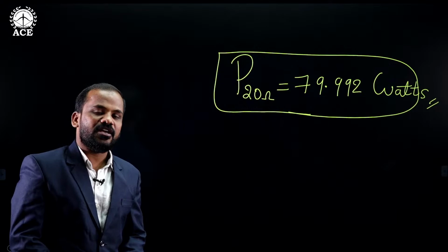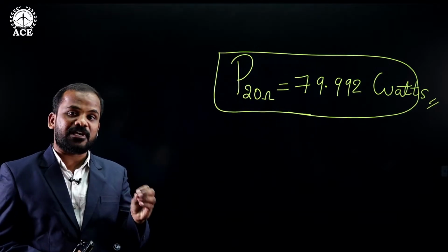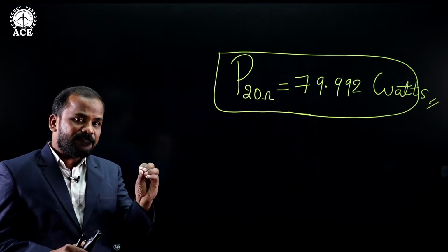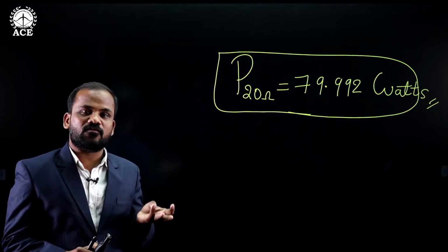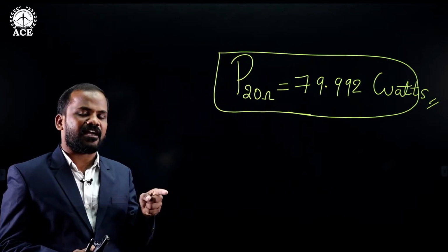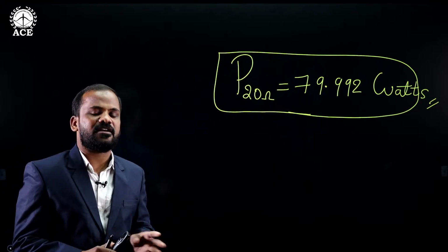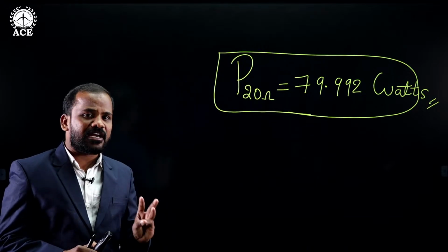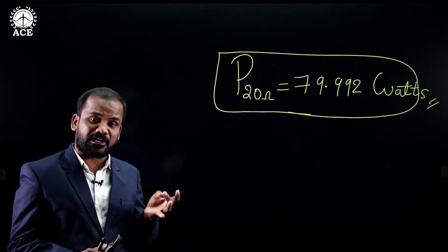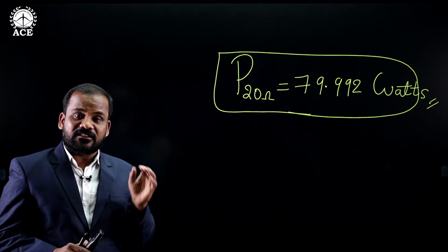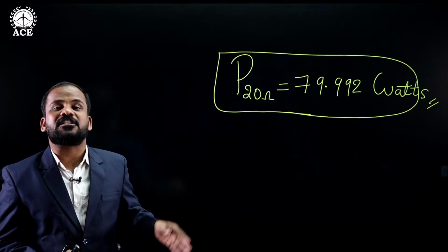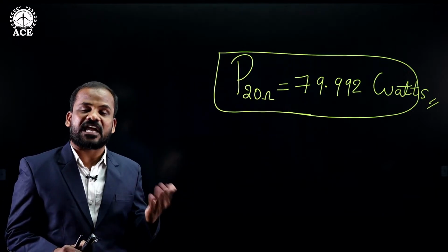Okay. So this process is applicable for any DC network if the network consists of multiple voltage sources, multiple current sources and multiple resistances. Once again I am finally defining the statement: in any linear and bilateral network consisting of multiple voltage sources, multiple current sources and multiple resistances, the response in any branch of a resistor is the sum of the responses while individual sources act alone.